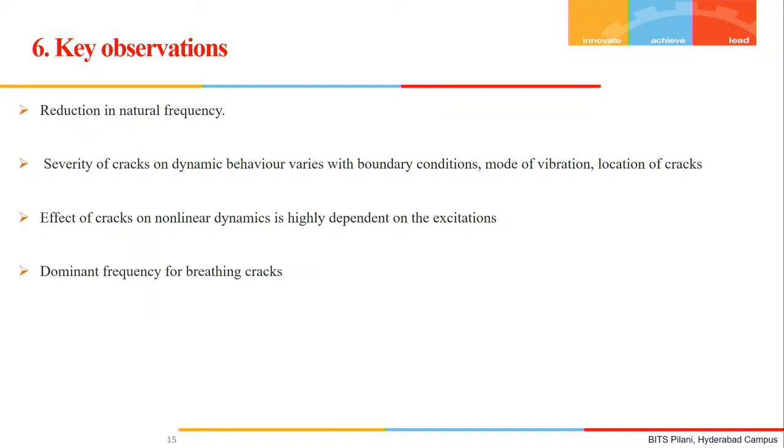And dominant frequency is one concept which is also a takeaway. If there is a crack, generally cracks are breathing in nature, the fatigue cracks. So the resonance which we structural engineers generally try to avoid will be closer to the dominant frequency, not to the frequency which we get from the open crack modeling, or from any bilinear modeling. So it is basically closer to the dominant frequency, and the dominant frequency is relatively different from what we get from the open crack modeling. So that is all for this talk.